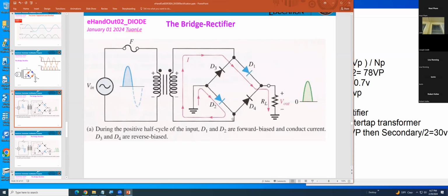Okay, now when I talk to you, that 50 volt, for example, what is this side? Oh, negative 50. Right, and this side will be zero. And zero is higher than negative 50, so D2 is on. That is explained to you: D1 on and D2 on.